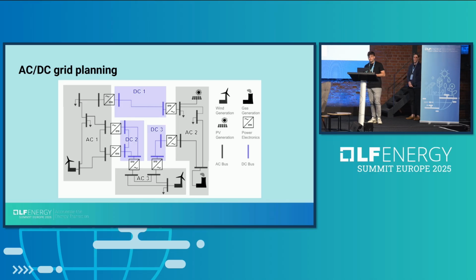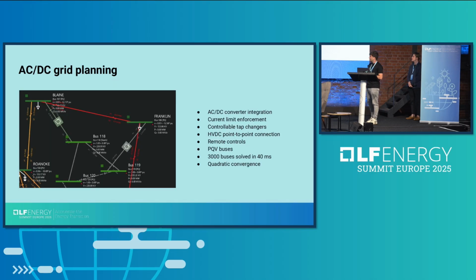So we used our own formulation in which we modeled the AC and the DC systems as a single system instead of separating the AC and the DC side and then solving sequentially, which is done in the state-of-the-art solvers. By doing this, we have to model the VSCs, which are present in the hybrid grid.